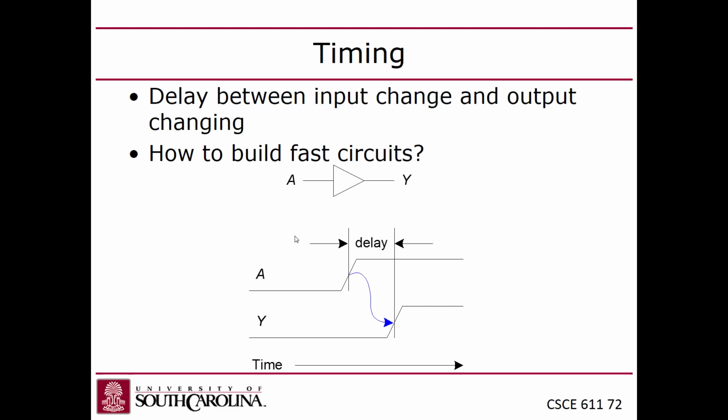But it's non-trivial, because gates are fundamentally capacitors. And they have capacitance and, of course, resistance in them, because there's resistance in everything, unless it's a superconductor. And so anytime you have capacitance and resistance, you have an RC circuit. And in order to charge up the capacitance, it's going to take whatever the resistance is times the capacitance in seconds, charge or discharge.